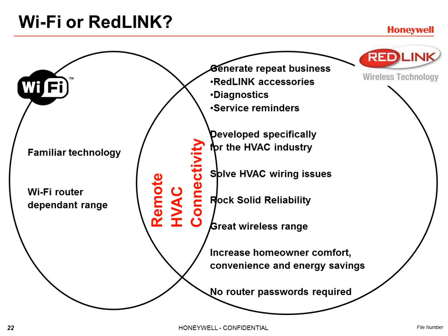So the Redlink product is nice because it becomes wireless. You don't always have to run wires to this thing. Any Wi-Fi thermostat we're talking about today is going to be 5 wires, which sometimes it's not a problem, and other times it is a bit of a problem. So Redlink can be wireless, and that makes sense.